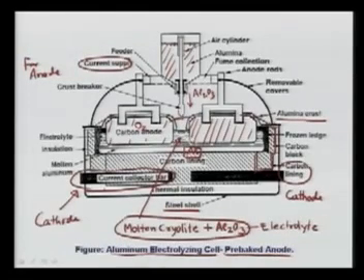So first you break the crust, and this hopper kind of thing you see here drops the alumina in. Once the alumina is dropped, it dissolves into the cryolite and makes electrolyte. The electric process goes on, aluminium is produced, and the oxygen goes to the anode, which is made of carbon and is continuously consumed.